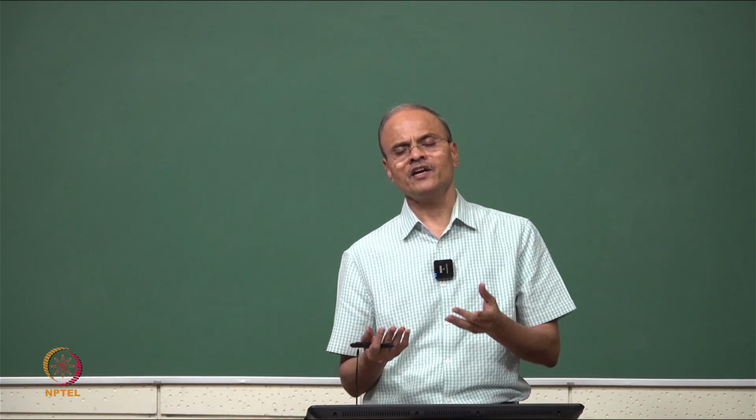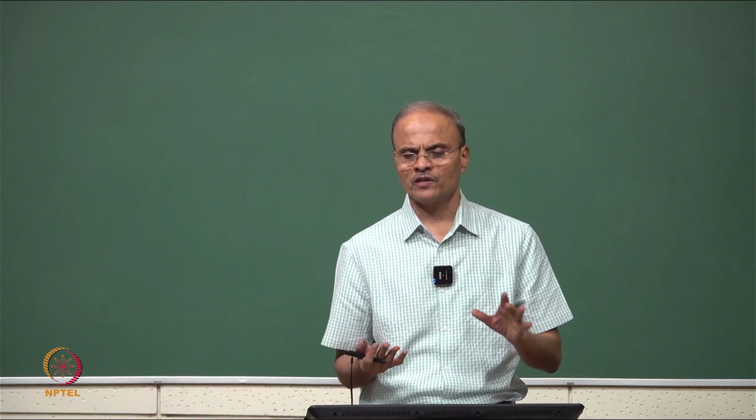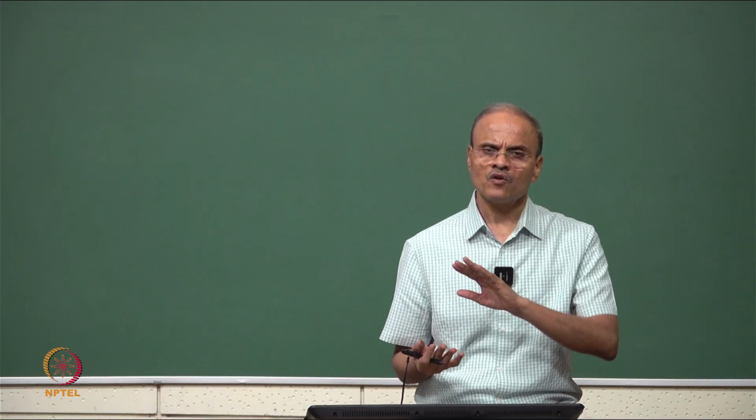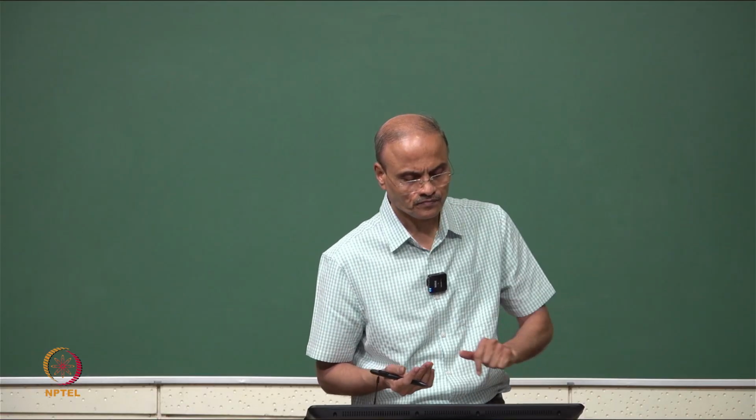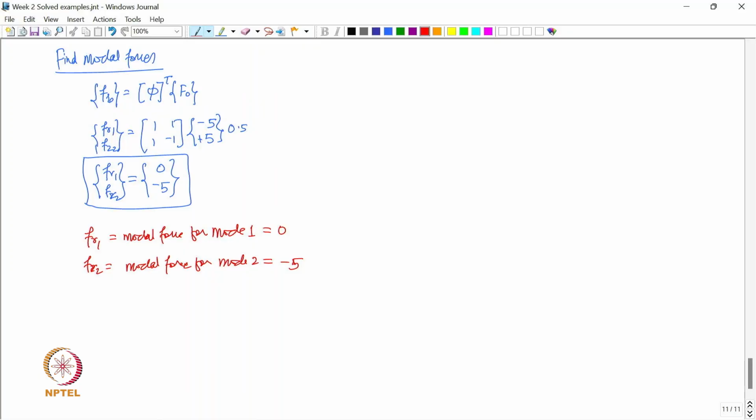So, that is a very important insight we have got, and Fr2 is the modal force which is non-zero in this case, and that is being excited by the applied force vector, correct. So, the force vector that has been applied is such that it is not exciting the first mode at all, it is exciting only the second mode. So, the next thing is, now we need to find the modal responses, correct. Let us find the modal responses.